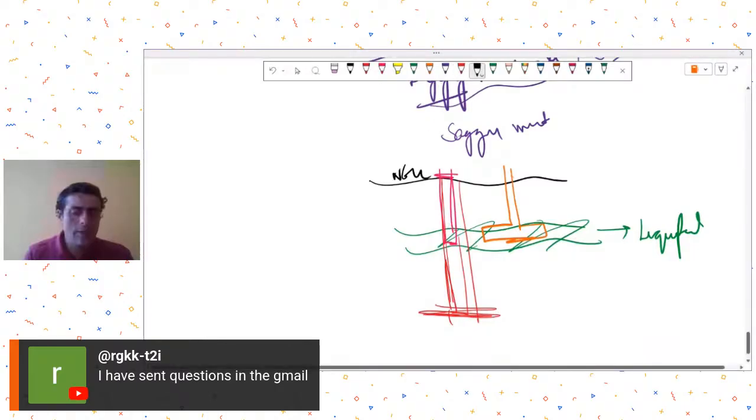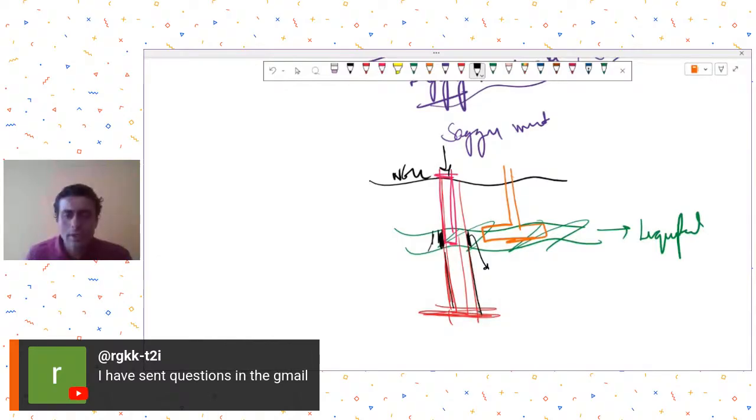And then in capacity calculations, I will have to ignore. Let's say this was a case of friction pile. So this strata of soil will undergo liquefaction, so I will ignore the friction that will be offered by this zone, and accordingly I will calculate what is available to me, assuming that this zone has undergone liquefaction. So I calculate my capacities disregarding the resistance offered by a particular soil strata which is expected to undergo liquefaction. This type of thing, usually you will get assistance from geotech engineers, and they will help you with this.